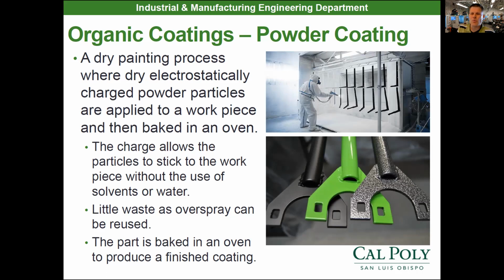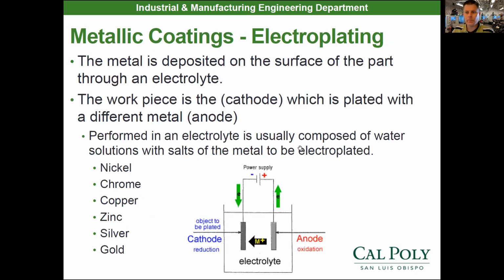It's hard to chip or scratch powder coat compared to a paint coating. Although it can be chipped and scratched, once it is, there's really no fixing it. You can't just use touch-up paint. It's different because it's basically one substrate that formed a bond once it received that energy in the oven. So that's what powder coating is all about.